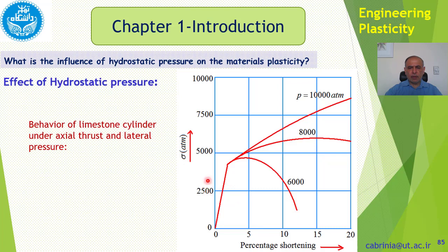And at 10,000 atmosphere, you can see that it increases and doesn't break. Why does this happen? Because pressure prevents cracks from growing. Crack growth is arrested under pressure. Okay, and the reason that materials break or fail is due to the crack growth.